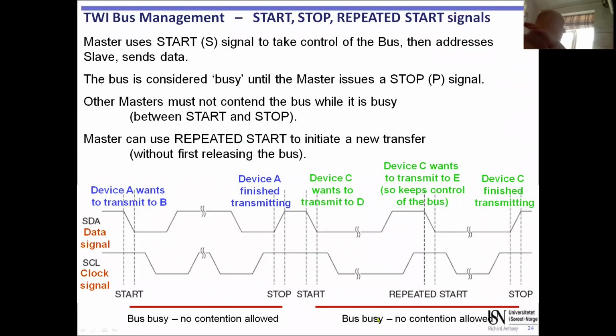Okay, I won't go into great details with this either because it's complex, but you need to have a general understanding of how it works. So I'll keep this at a high level, but I want to make sure you understand the basic idea. You have a data signal and a clock signal, and these are two separate wires, and this is why it's called two-wire interface. Okay, so one wire is your data and one wire is your clock. And the device that is transmitting is automatically labeled as the master. That's really what is happening. The one that is transmitting is in control. And the one that is receiving data is basically just following what the controller is doing.